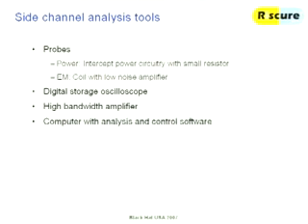Okay, so the question is getting from that signal to, well, your secret keys, basically. The first thing you need is the probe that I showed. You can do it in power, by measuring current through a resistor. Then you need a scope. There's one here, a USB scope. It's a bit more expensive than the one shown yesterday. I'm not sure if you saw the talk about the wireless devices. This scope is about, I think, 1,500 euros. It's a 200 megasample scope with a bandwidth of about 100 megahertz. So that's what we will be using in the measurements.